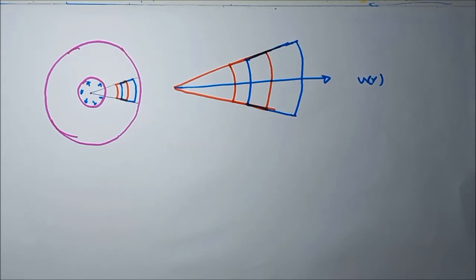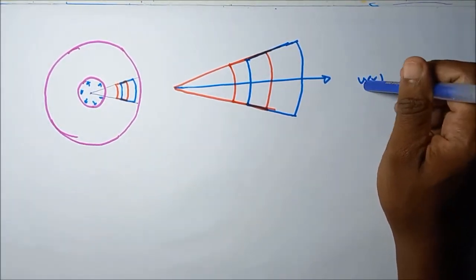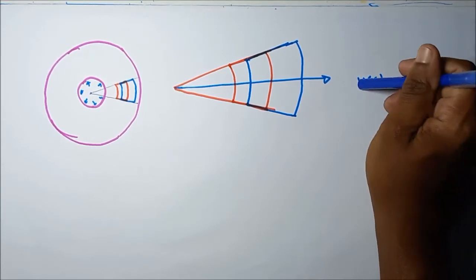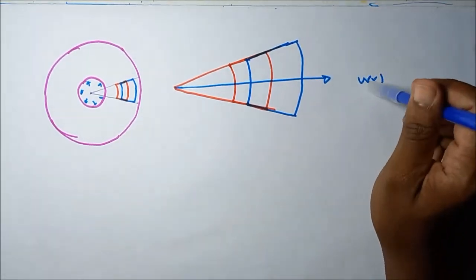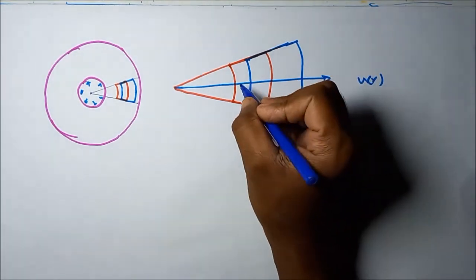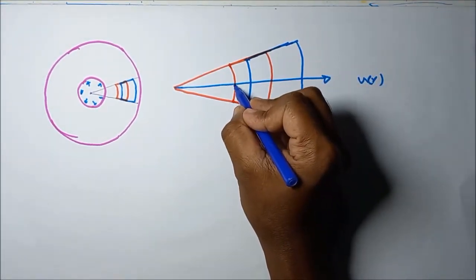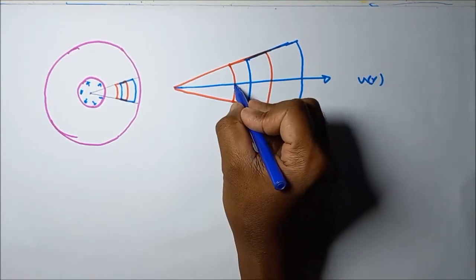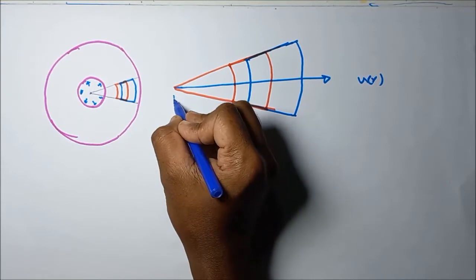When a cylinder is under pressure, the displacement is represented by the displacement function u(r). Then what is the strain in radial direction considering this displacement? If you take the radial position to this position, the distance is equal to r.